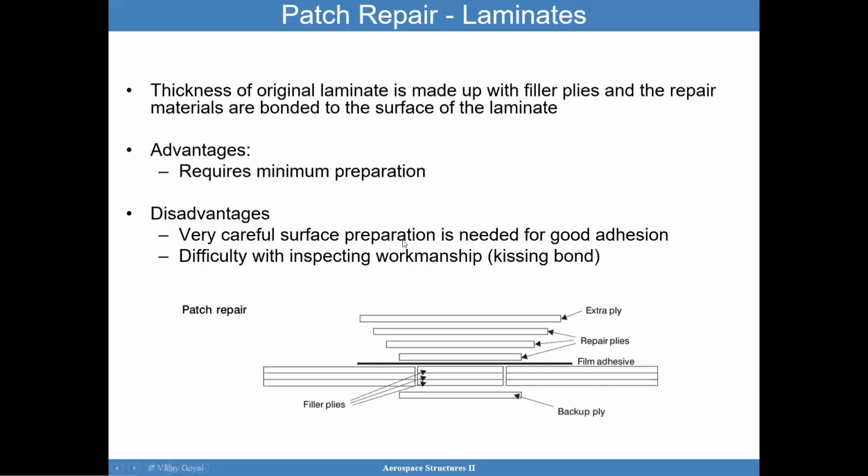Very careful surface preparation is required for good adhesion, and you really need to inspect the workmanship. You need to inspect the work to ensure that you have good bonding. And so it's really a good idea to have an extra ply just in case. You want to make sure that the materials are compatible at the interface.